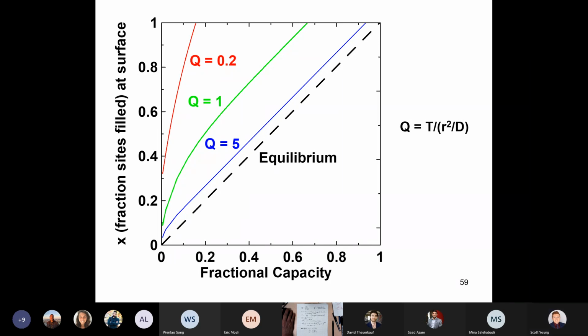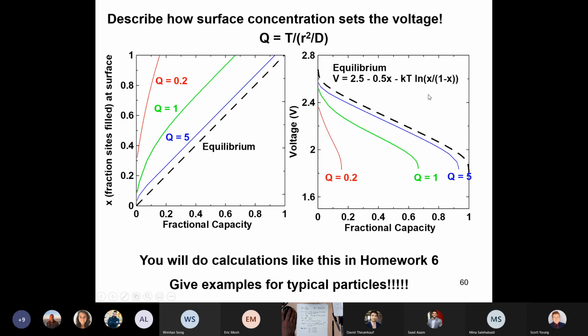Change R? Yeah, you change the particle size. So if you're in a situation where the limitation in your ability to charge or discharge fast is the particle size, you just make the particle smaller. And you'll find that high-rate lithium-ion cells have a smaller particle diameter for both the positive and the negative side particles. Instead of like 15 microns at the positive side, they'll be more like 5 if you really want to go fast. Okay, so then